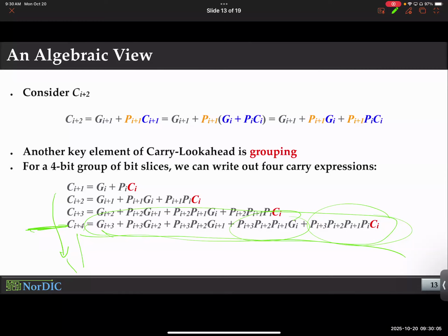Nobody just designs something and then, oh, it doesn't work. You will simulate and see how much we can handle. Can we do 5 bits at a time, 4 bits, 6 bits, 8 bits? How many bits will be the most optimum situation? That will still be faster than ripple carry, but you see my point, I hope.